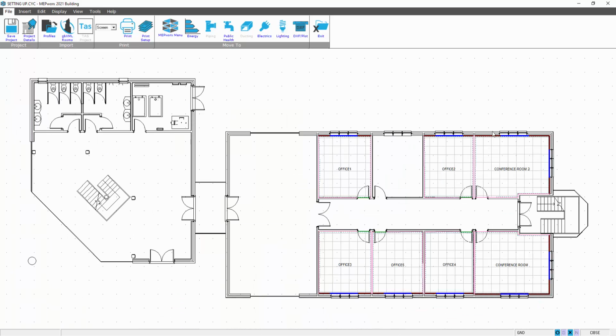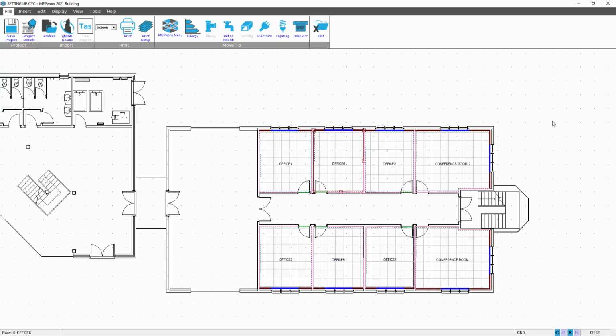Now we have our rooms defined. And just to complete the process, I would grab that room there, copy room, drop it into position, right button click, flip room vertically. And that sets me up nicely to show the next video on copying between floors.